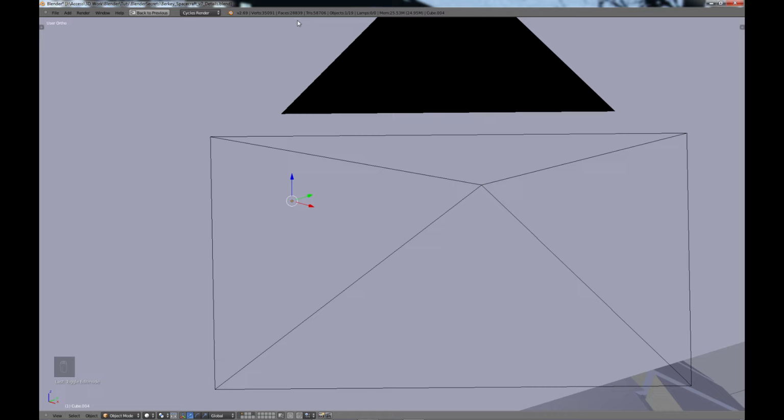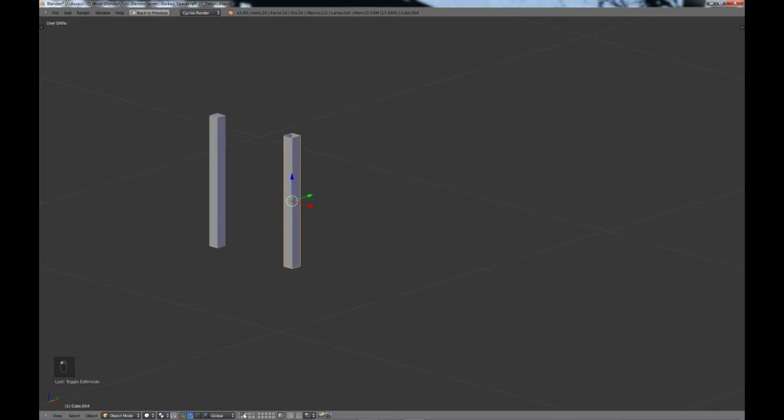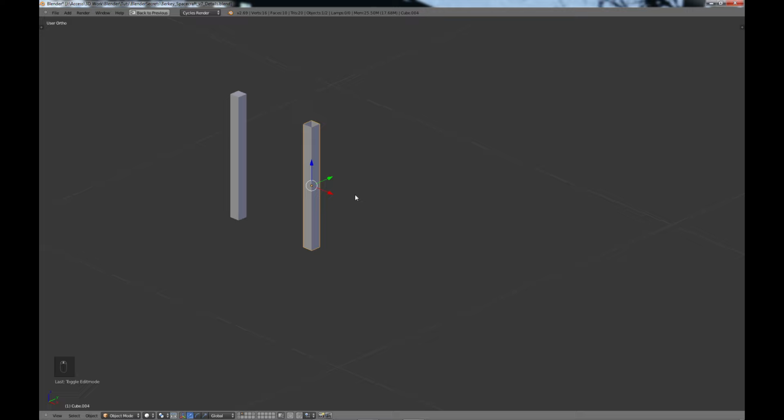You see that we have right around 28,000, just over 28,000 faces. So in adding all these details, our polygon count is going to just start going through the roof. So we need to be thinking ahead as far as how we need to create these in order to reduce our polygon count. As we're modeling, you just want to think ahead in that way to try to reduce along the way.